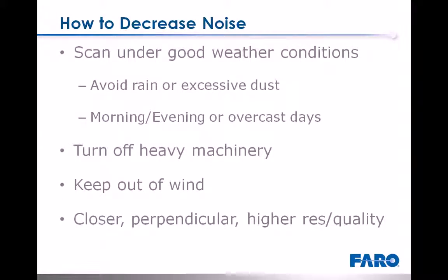The best way to avoid noise is to avoid getting it in the first place. Some of the environmental factors we just discussed can be alleviated while scanning, or at least improved upon. Try to scan when there is less dust or moisture in the air, and try to scan under less bright conditions if it's possible, by scanning in the morning or in the evening, or on a more overcast day.